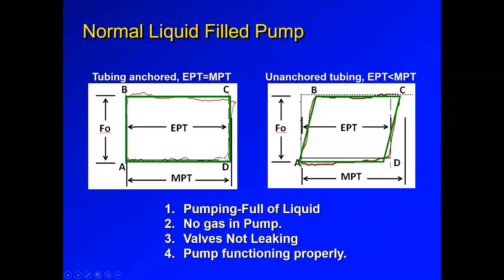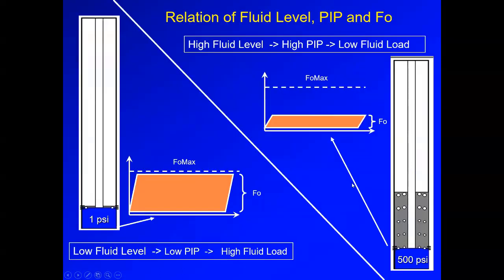But the fluids only move from the chamber to the tubing across the traveling valve when the traveling valve opens. And in this case, the traveling valve opens later. That's what we call, after the traveling valve opens, the effective plunger travel. So not all the stroke is used to displace fluid to surface. Only when the traveling valve opens does the fluid move from the chamber across the traveling valve into the tubing. So that is the difference between maximum and effective plunger travel.